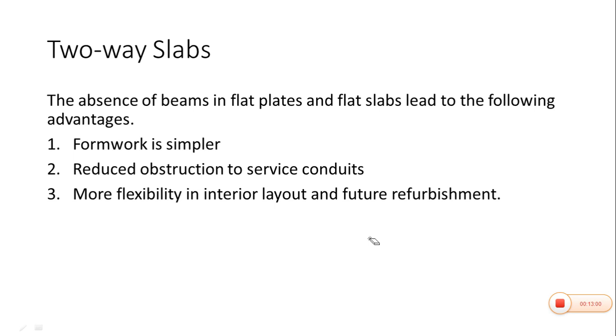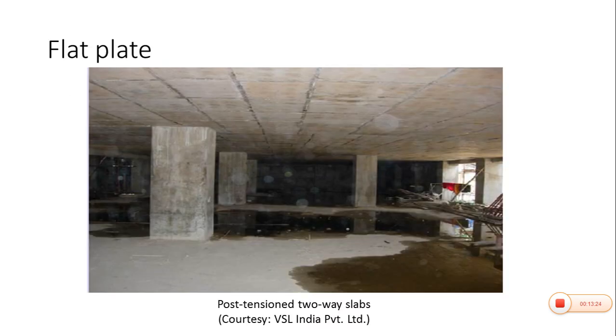It gives us a plane surface, and that plane surface provides more flexibility for the interior layout, because if we have projections in the layout, we cannot use that area effectively. So that is the advantage of flat plates or flat slabs.